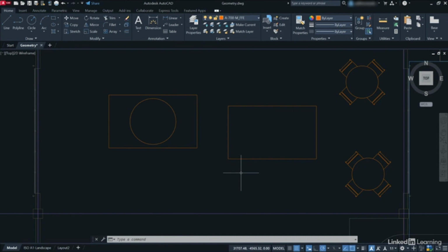But you can see there now that I've created a rectangular table using just that polar tracking set to 90 degrees. Now, if I go and set ortho now, if I come down here, the ortho icon is here. There's ortho mode, orthogonally. So if I click and switch that on, you'll notice my polar tracking turns off. You cannot have ortho on and polar on at the same time and vice versa.